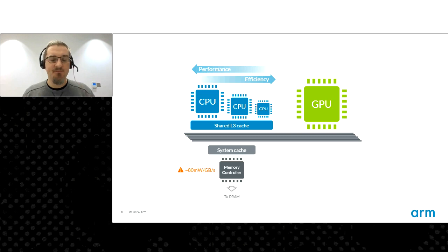There's a GPU, obviously generally a big processor, and the diagram's deliberately large here. It's a nice data parallel processing domain. You can put down more shader cores. The implementation parallelizes for you. So generally you benefit from silicon area without the application doing a huge amount. High-end designs can have a much bigger GPU, spending quite a large amount of silicon area on it, because you will see the performance uplifts.